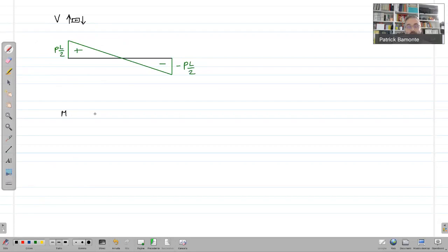For the bending moment, since I gave you full freedom to decide your own convention, you have to specify what convention you use. Now, my convention, the Italian one, is to plot the bending moment diagram on the tension side. Simple equilibrium equations written on portions of the beam will clarify that the bending moment is always positive.